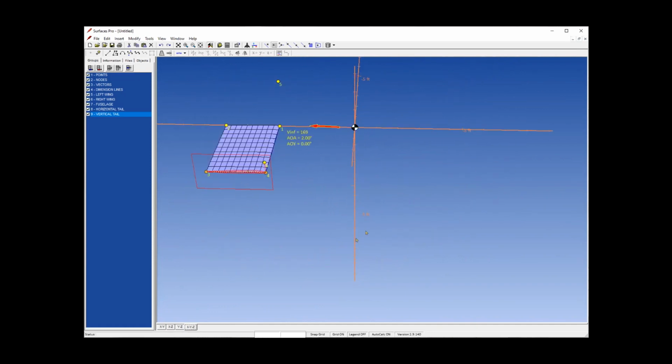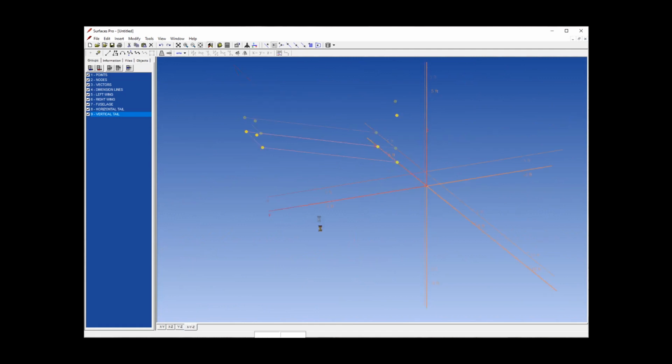The program does what we told it to. Our mistake is that the control point is no longer normal to the wing plane. You can see that the tip airfoil is now slanted with respect to the wing plane. We have decambered the airfoil, modifying its properties. The same actually holds for the root airfoil. It too is no longer normal to the wing plane. It too is decambered. This is a very common mistake I see my students make all the time.